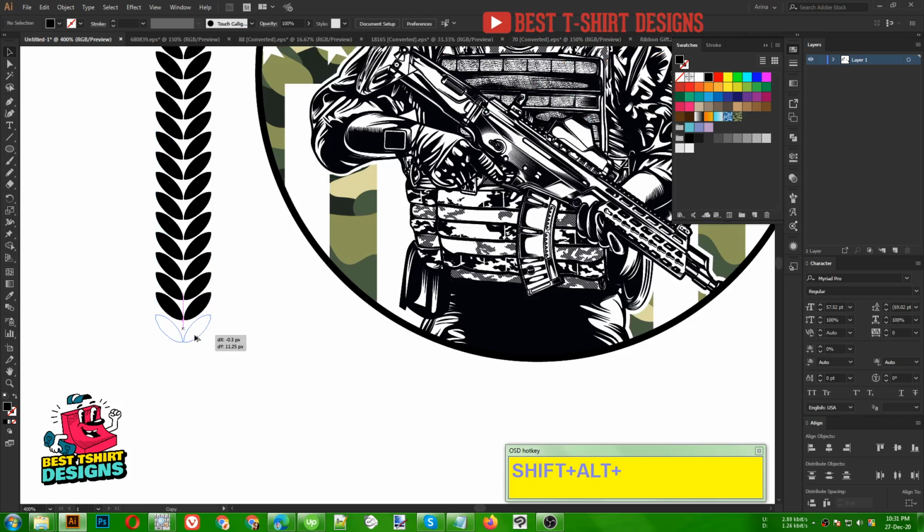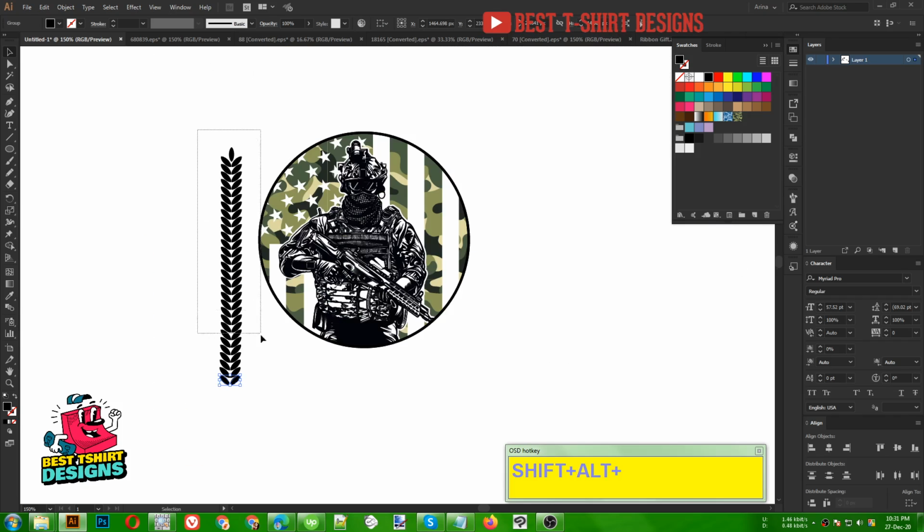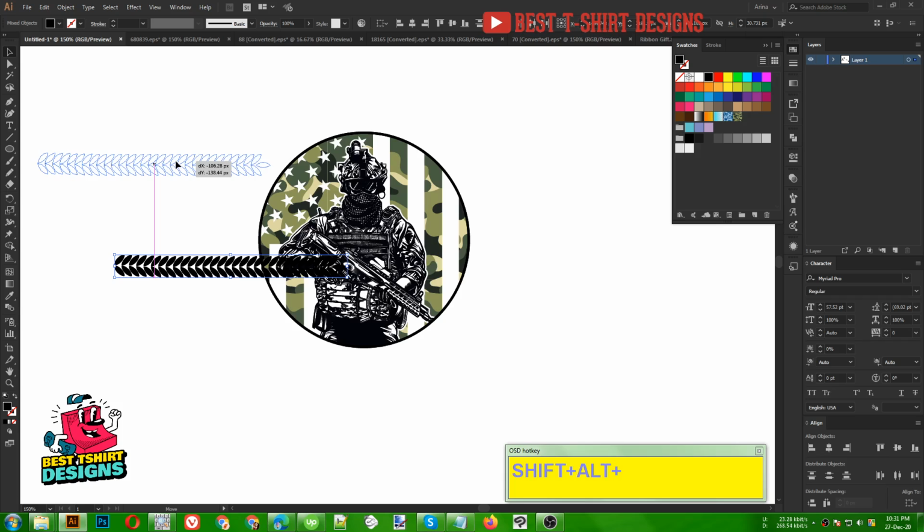So if I just bring a copy here, then press Ctrl D a couple more times, something like this. That is good. So this much will work for us because I want to arc it with the ellipse here. So that's why I am making it bigger.